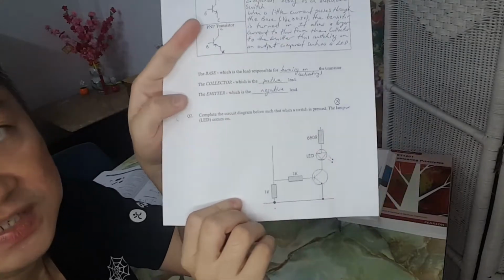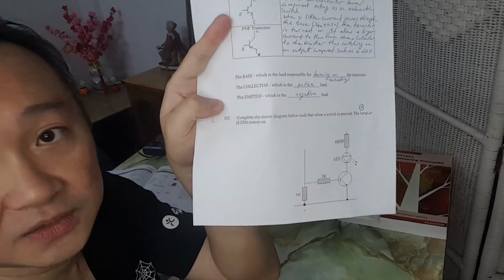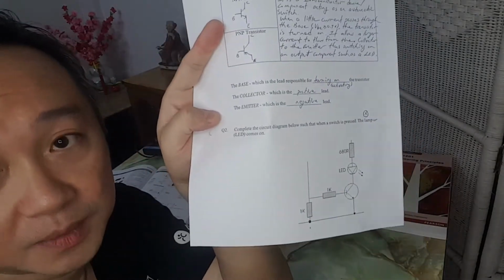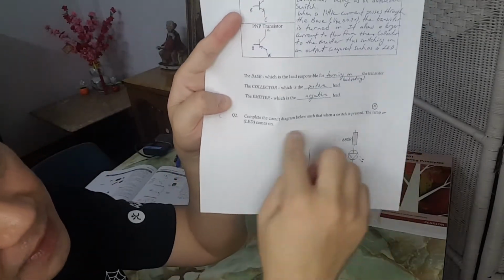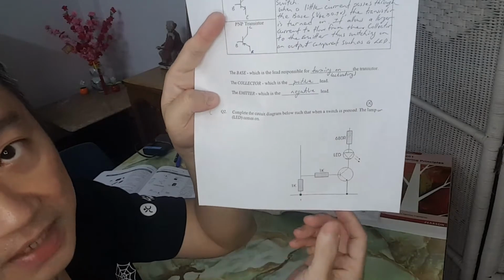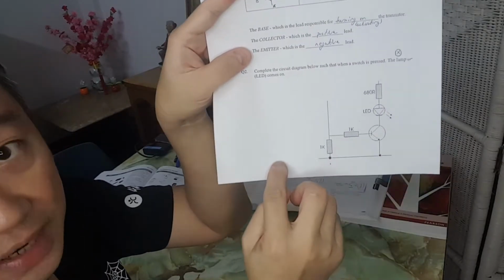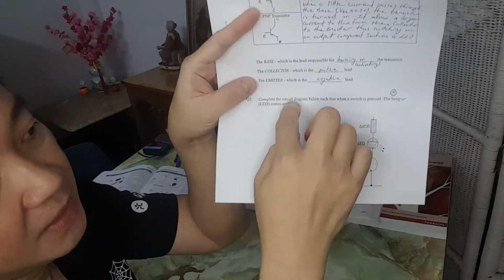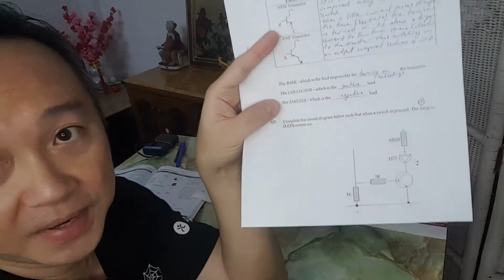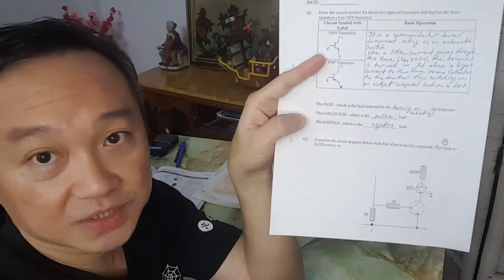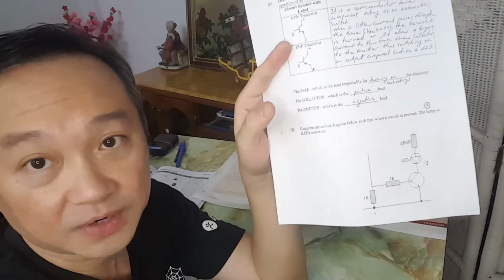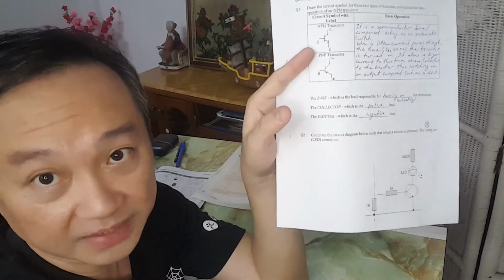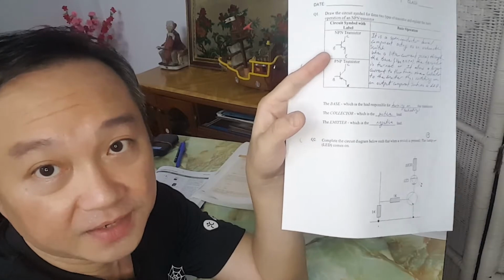And also you notice that there is no power supply. So in this case, you will have to provide the power supply by drawing the symbols, as simple as just labeling the plus, maybe 9 volts, and ground or 0 at the bottom. Now, a point to note is that many students have this misconception that power supply, your DC, your batteries, your cells, are part of the input or are input components. In fact, power supply actually stands alone.